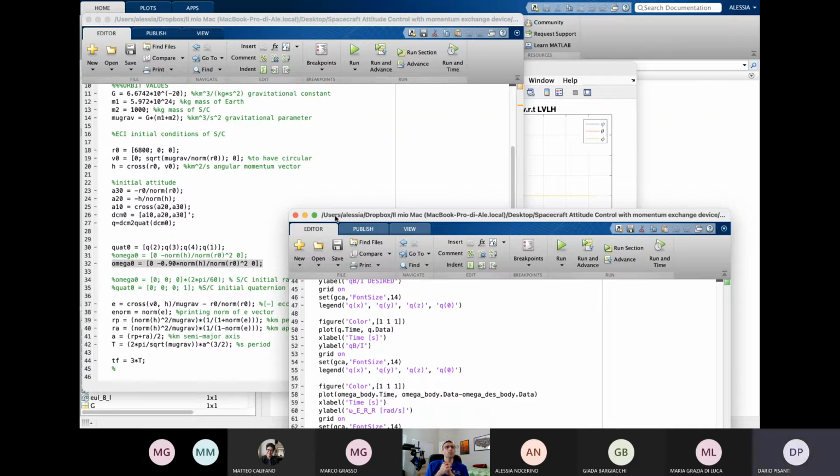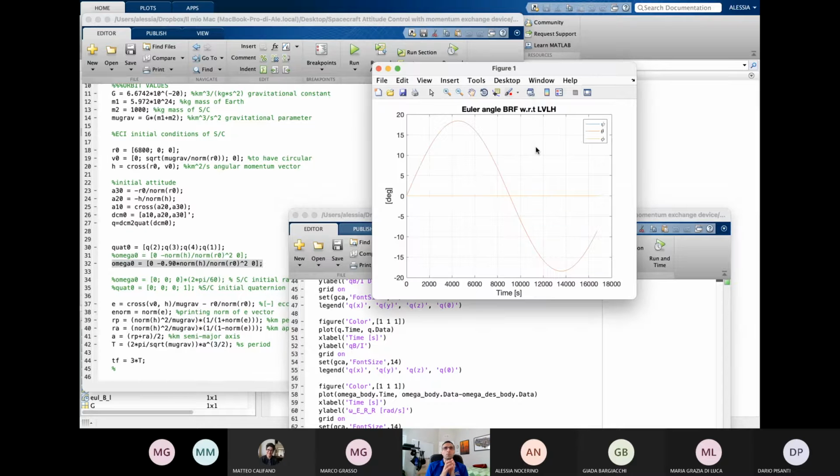You start aligned, but you're a little bit slower than LVLH, and that's one way. You can also start with the same angular velocity as LVLH and a little misaligned. Maybe you can play with different initial conditions. The goal is seeing the oscillation, and for that you need a non-zero relative motion with respect to LVLH. You cannot be perfectly aligned and also moving the same exact way, because then you're not exciting the pendulum behavior. But if you excite it, you need to do it carefully so that it remains small enough that you don't go outside of the region where you can say it's stable, right?